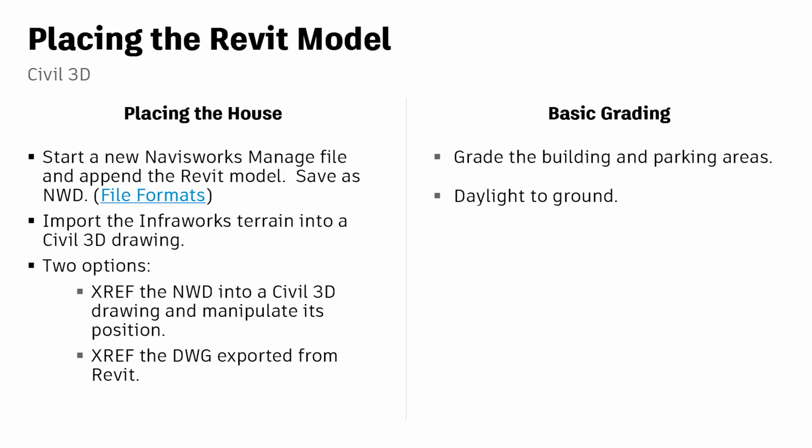In fact, you can't actually XREF a Revit model into Civil 3D. There are a couple of choices, one being the Revit designer exports to a DWG, which can then be XREF'd. Or we can append a Revit model into a Navisworks model and save it. The Navisworks model can be XREF'd into AutoCAD.